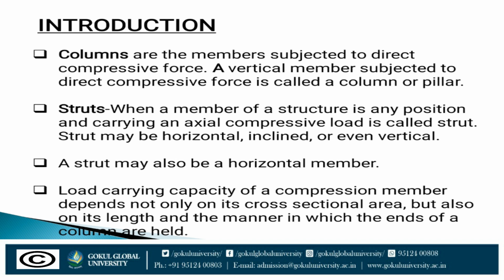Second one, strut. When a member of a structure in any position is carrying an axial compressive load, it is called a strut. A strut may be horizontal, inclined, or even vertical. Load carrying capacity of a compression member depends not only on its cross-sectional area but also on its length and the manner in which the ends of the column are held.